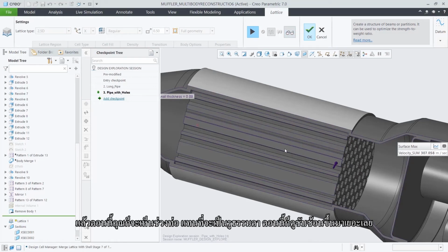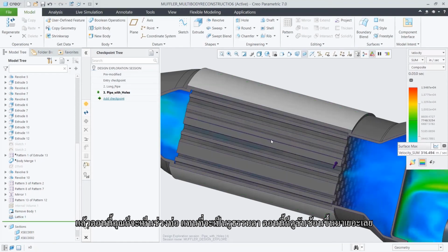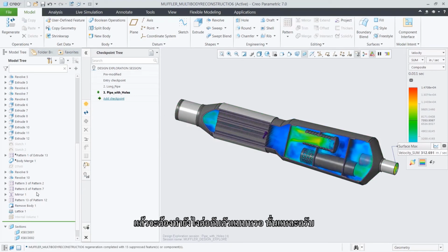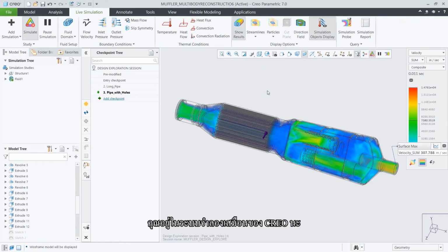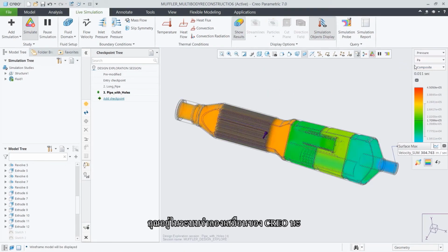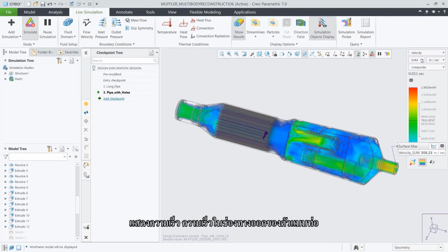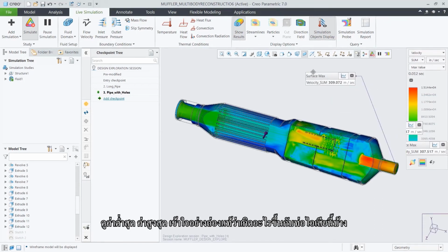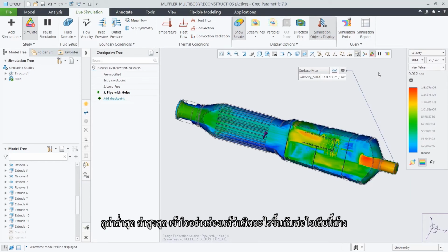And now you can see that pipe section, instead of just simple holes, is now a whole lot more complex. We've got a hexagonal flow body through there. So now, what did that do to my model? Well, that's just it. You're in Creo Simulate Live. I can say, show me the pressures. Show me what that does front to back. Show me the velocity. What's that doing for our exit velocity? A lot of different ways to look at it. Look at the min, look at the max, and really understand what's happening with this muffler.